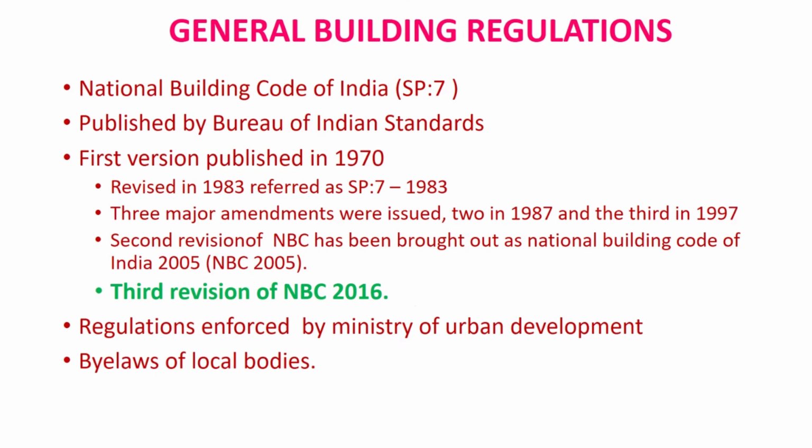Now this is with respect to ceiling fans. Many times we are required to provide them, and again we are not aware of the provisions. Unless otherwise specified, the clearance between the bottommost point of the ceiling fan and the floor shall not be less than 2.4 meters. If you have a ceiling fan installed, the height from the floor to below the fan should be at least 2.4 meters.